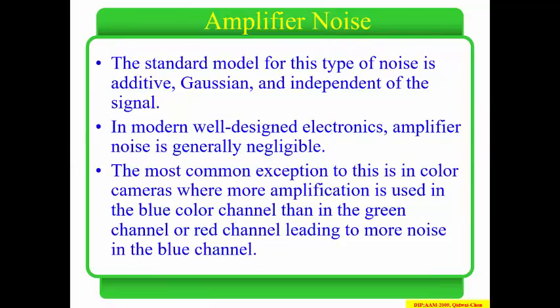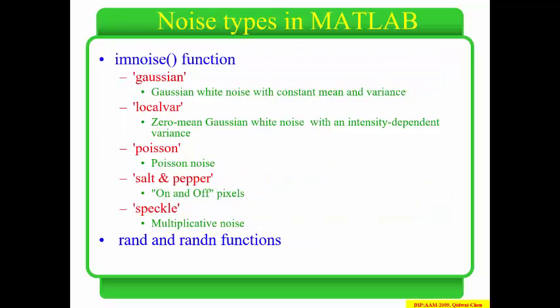Also we have the amplifier noise. This is a well-known noise. After capturing this signal, it is of low level, and I need to raise its level a little bit, so I will use an amplifier. All of the amplifiers that we have will inevitably add additional noise. But how can I differentiate between one amplifier and another? It is the ability of the amplifier to suppress this noise. What do I mean by suppressing the noise? Trying to minimize the effect of the noise. We don't have any amplifier that can prevent the noise 100%.